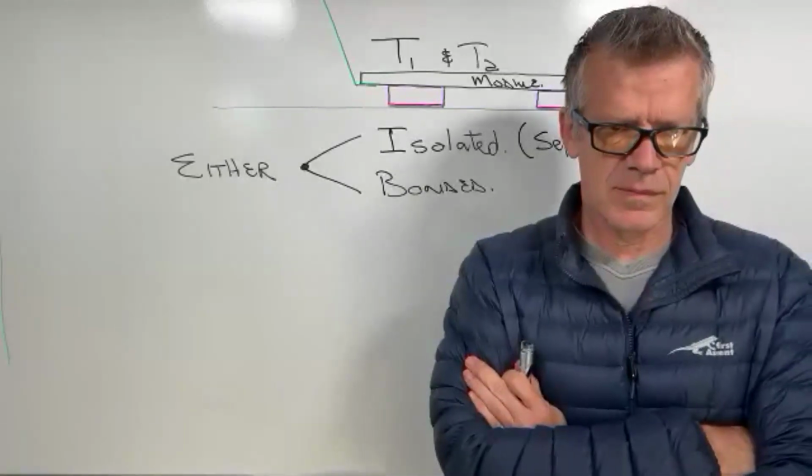The lightning protection standards and SANS 10142 actually say that if a lightning protection system is installed and it is bonded, which means you bring lightning currents into your system, you need to install a type 1, type 2 lightning arrestor. That's the theoretical part. The practical part is it's not economically viable to install class 1 SPDs, because for that inverter, if you've got 20 strings, you'll need to install 20 type 1, type 2s, at for example 2,000 Rand a pop.